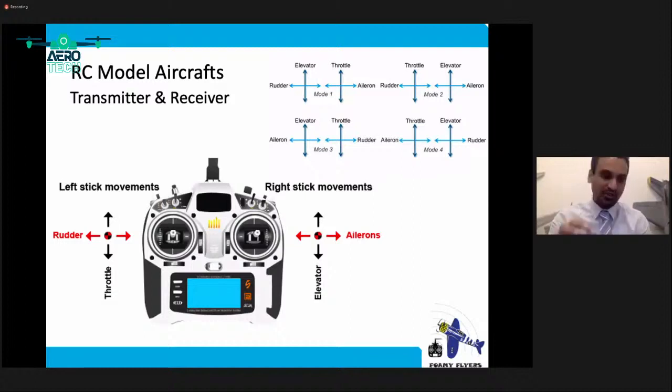However, once you build the aircraft, you need to find the CG of that particular aircraft. Normally, the CG, or center of gravity, will keep the aircraft straight and level. This is a basic calculation: the CG is measured from the leading edge of the wing, and should be around 1/3 of the way back from the leading edge.